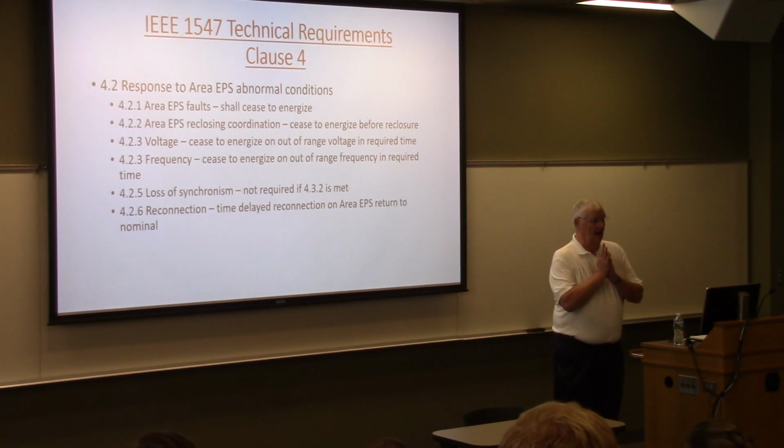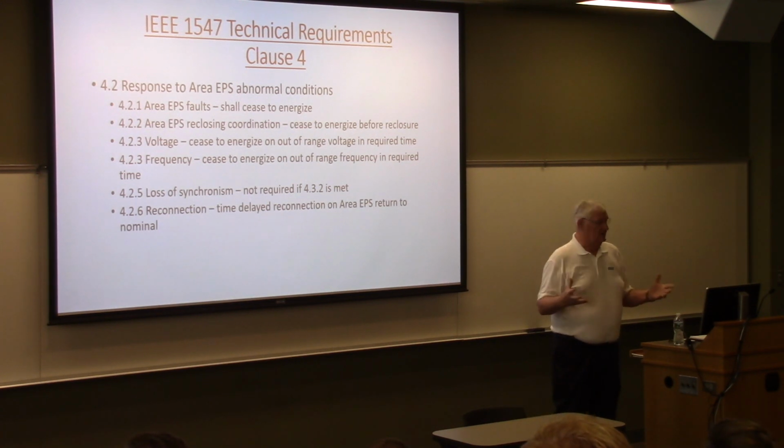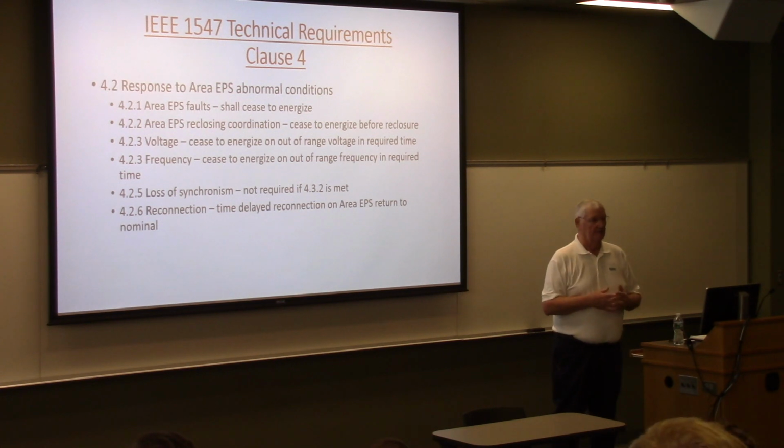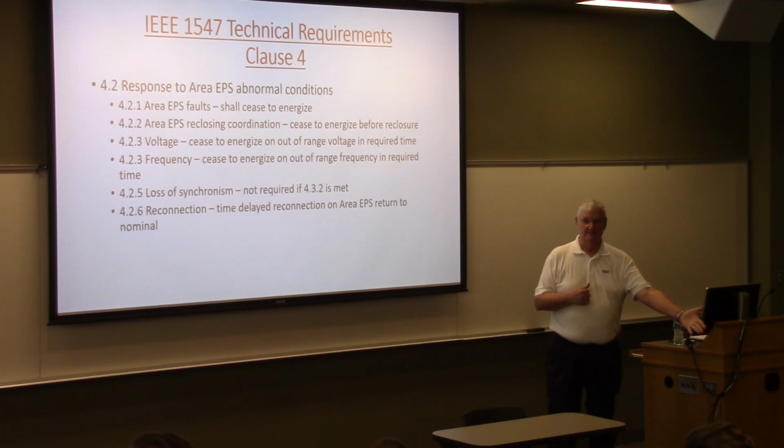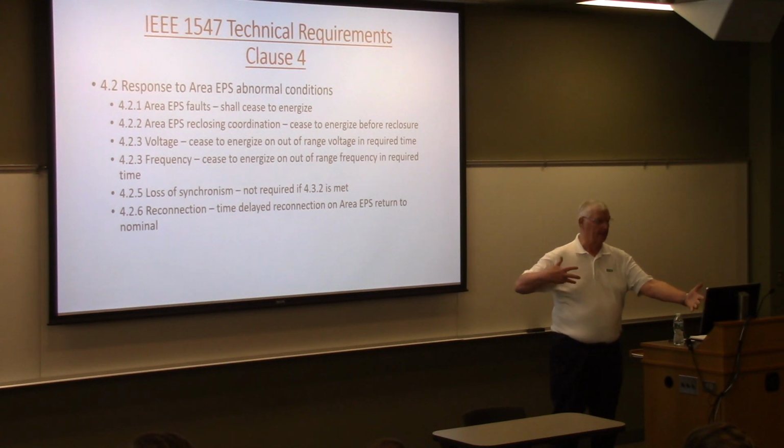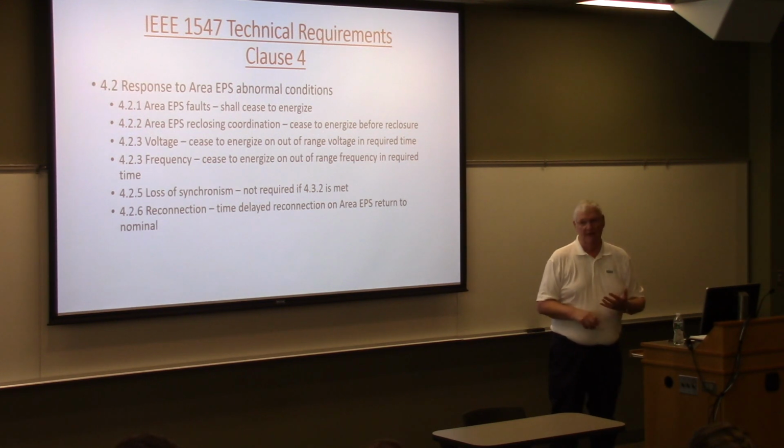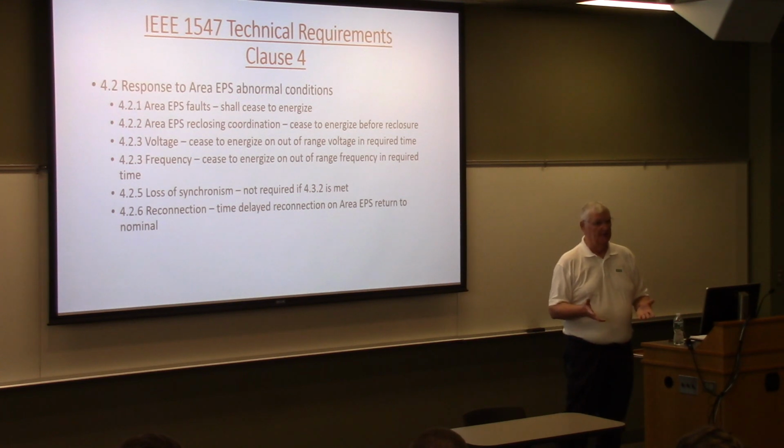Yes. And an unintended islanded system is if you've got a nice sunny day going and your system's feeding power into the grid and all of a sudden the grid disconnects and leaves you hanging out here. You've got to be able to detect that and disconnect from the grid. And it's important that you do that quickly for equipment protection and for personnel protection. You don't want to be feeding power into an area of the distribution grid that the utility company thinks is dead, because that kills linemen, and that's not a good thing to do.